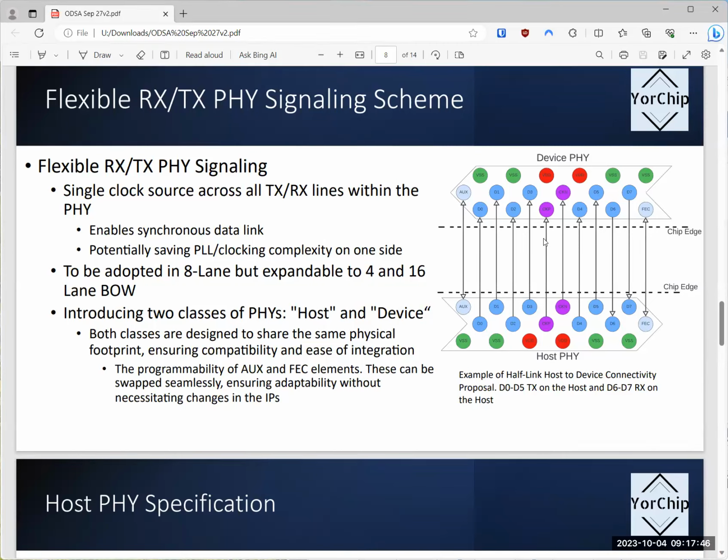If you just say there are always at least 2 pairs of clocks, and they're always unidirectional, then you can build a quote unquote normal PHY for each one of them, and you can have a bonus mode that for whatever reason doesn't need one of those 2 clocks. You'd pay a little bit of area for it, but it would be more straightforward, with very close to the area savings you intended, as long as you're talking to a 7x4 or whatever the quote unquote half width turns out to be. Does that make sense?